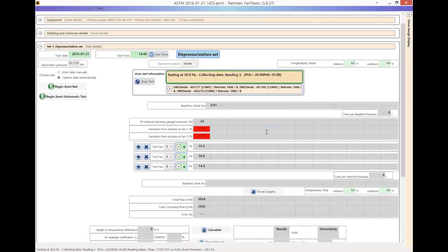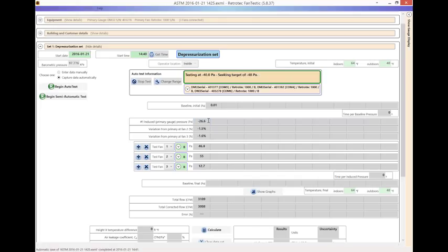It's not uncommon that it can overshoot those pressures. So what we see in the red, that just went from red to gray, the top is actually the pressures that are in the room compared to outside. It says that in the beginning, the pressures you had in your room with the gauge compared to outside were not close enough to your main gauge, but now they have fallen into place. I have some slides later which we're going to come back to. If you remember the red that showed up, we're going to talk about what that means in terms of where your fans are located, or that they're not actually able to gather the right data, or maybe something is separated with their tubing.